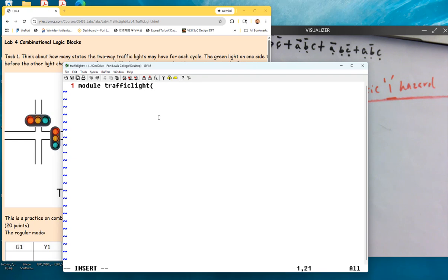Even though it seems like it's just computational logic, why do we need a clock? Because this is not running from top to bottom as a C program stored in the program memory on microcontrollers. This is just a snapshot, after you synthesize it, implement it and upload it to the FPGA. It's a digital circuit hardware.